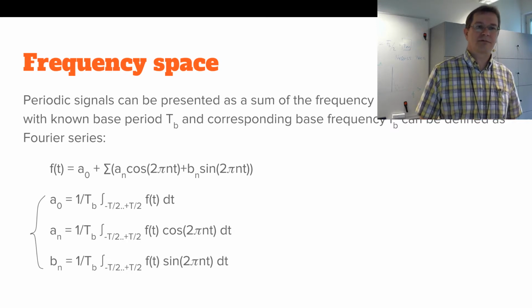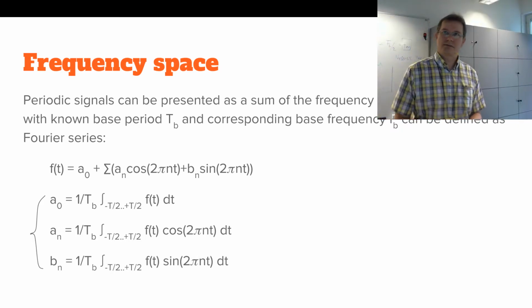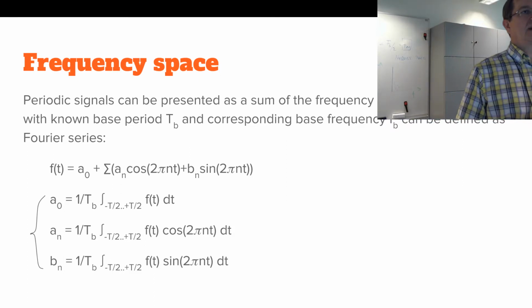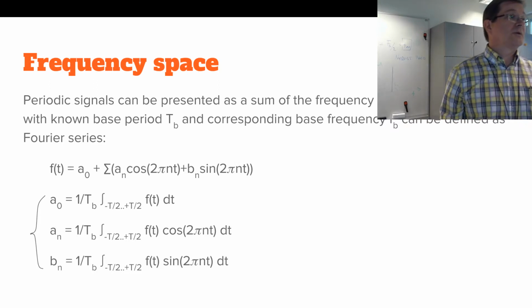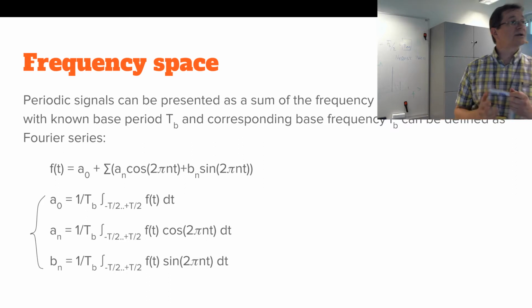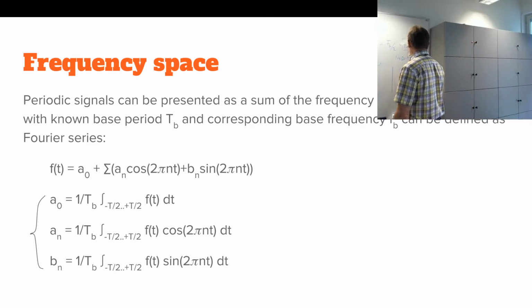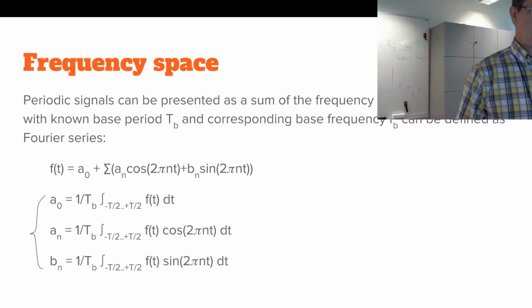Fourier series. Great. So basically, it tells you that if you have a periodic signal in continuous time, you can break it into different frequencies. And when you sample that, of course, the same thing happens as in continuous space. You have these harmonic signals, and of course, after sampling, you will also have the side lobes of those. But the formulas are beautiful, right?